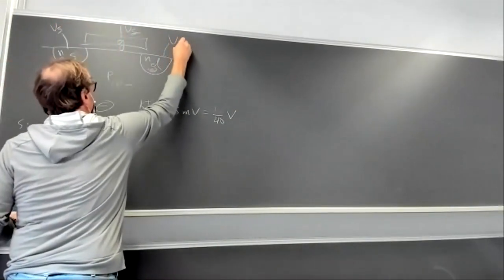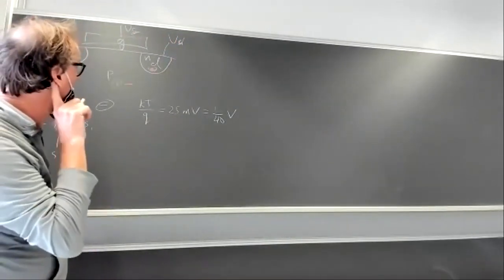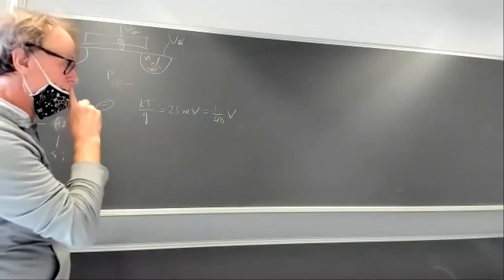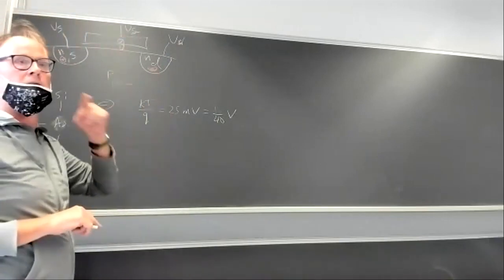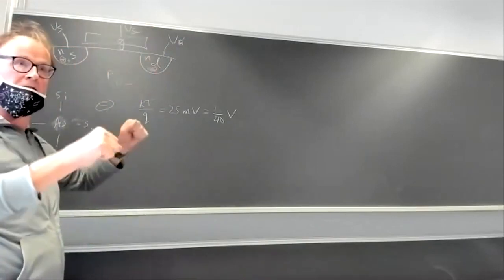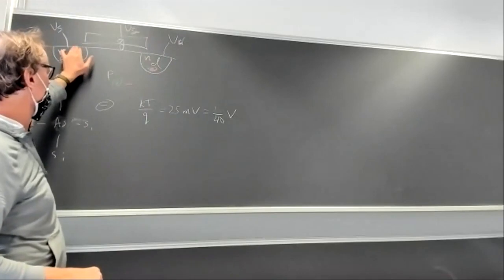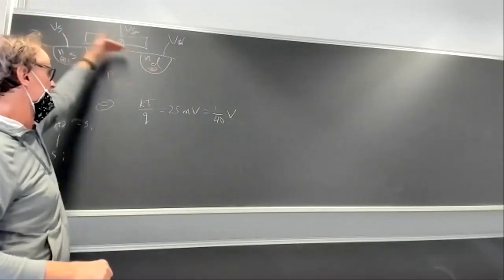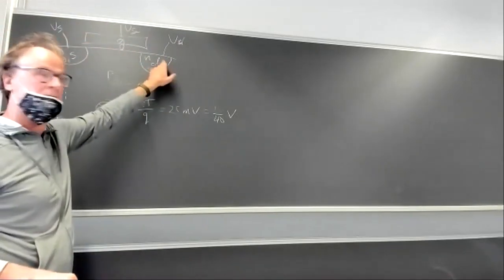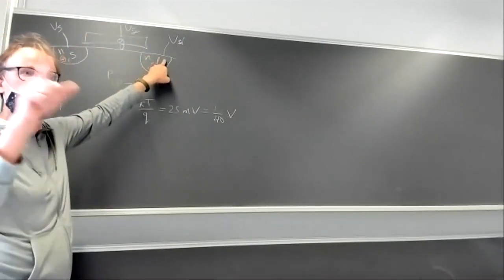What's the difference in composition between the source and the drain? The difference between the source and the drain? Nothing. I mean, except the voltage between them. But doping, the source is just, you're going to apply a voltage and that'll determine which is the source and the drain. If the electrons are coming from this end and going into here and falling out the drain, this becomes the source. If the drain's at a higher voltage, which direction will the electrons flow?